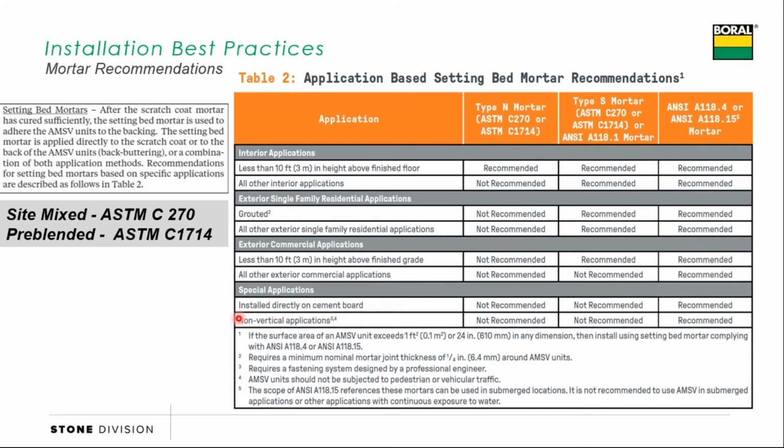Cement board, it's required to use a modified mortar over top of a cement board. I'll tell you personally, if I was installing a tight fit application on a garage front, knowing that, you know, with the garage door going up and down and a basketball hoop mounted on there, there'd be a lot of jarring and movement, but also people walking and playing underneath, I would move to that modified mortar. It's a small expense for that added insurance that stone's not coming off the wall.